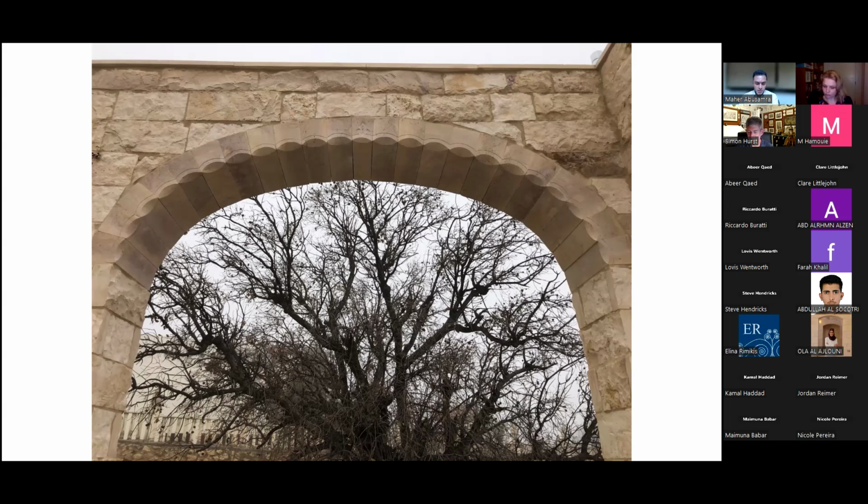The result was really fine for the thrust and for the forces. But in general, when you have a span, you go by 1/5 to get the width of the wall. So if you have another vault coming from the other side, it can easily be smaller, because you have two forces coming opposite of each other, so the result goes down.